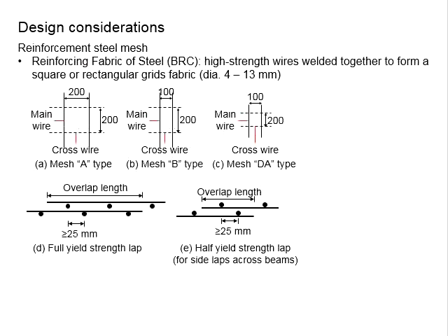Next, it will be the reinforcement steel mesh, which is typically used for the slabs. You know that the slab is a big piece of reinforced concrete member, which is in plank shape. You have relatively large cross sections of concrete as compared to the amount of reinforcement bar. Therefore, the reinforcement bars are normally adequately spaced out, typically in the range of 200 mm, 250 or 300 mm.